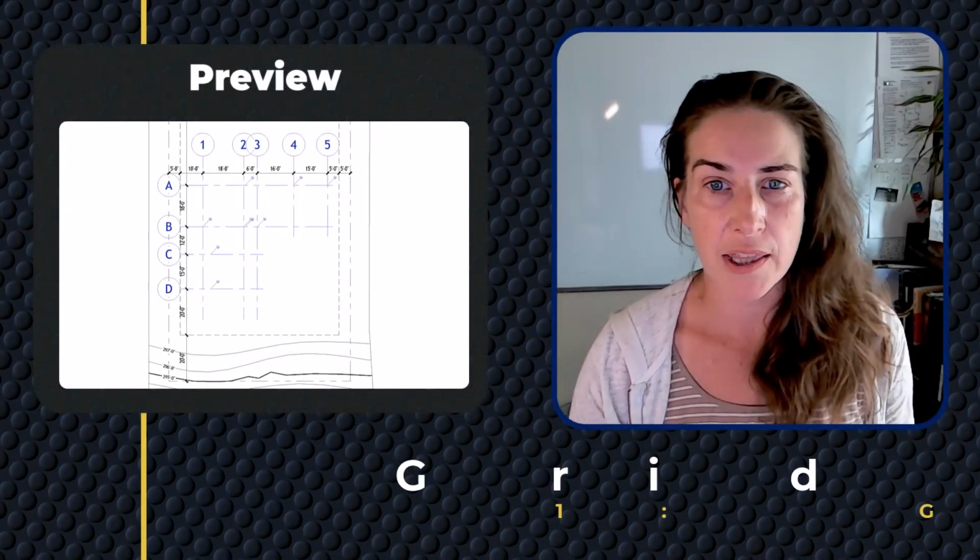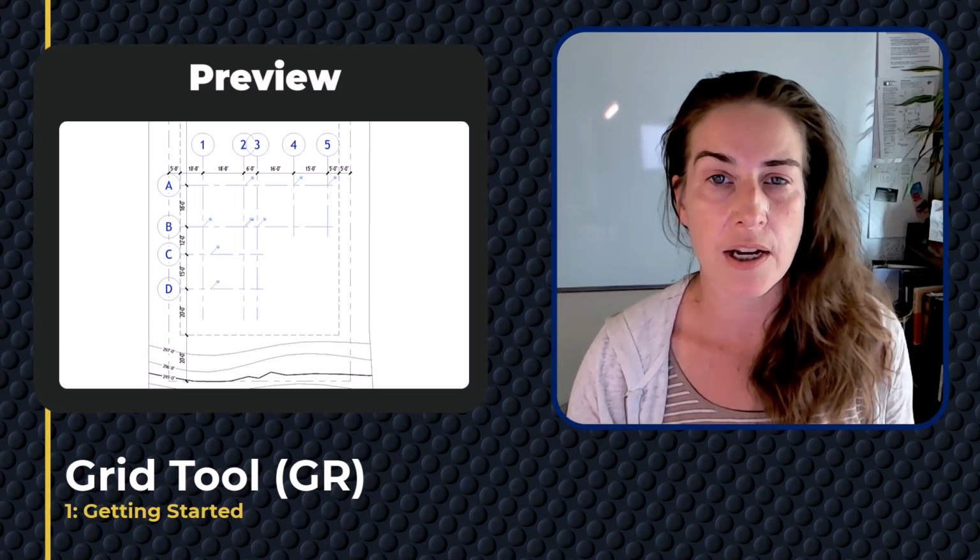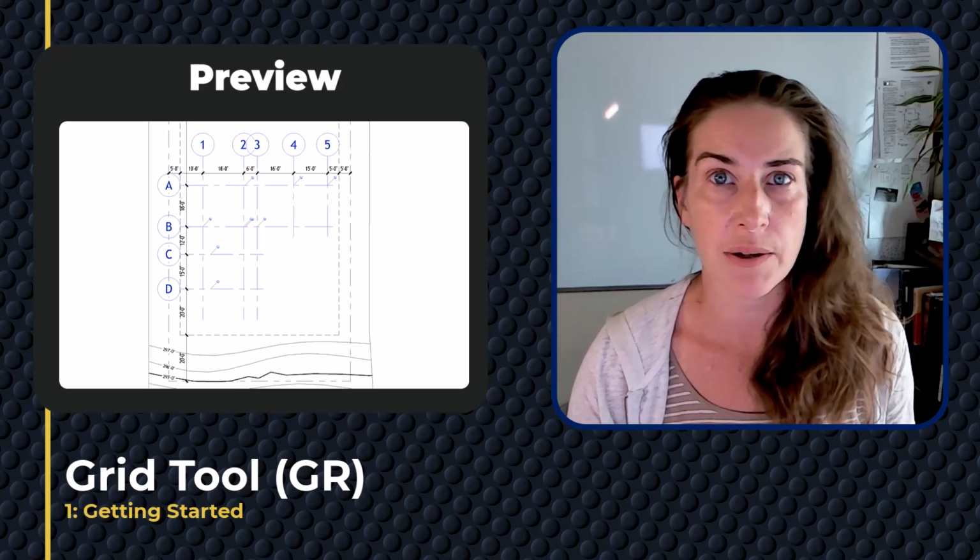As a reminder, in this video we placed grids and then used edit witness lines along with our dimensions to locate them on the site. I hope this helps.